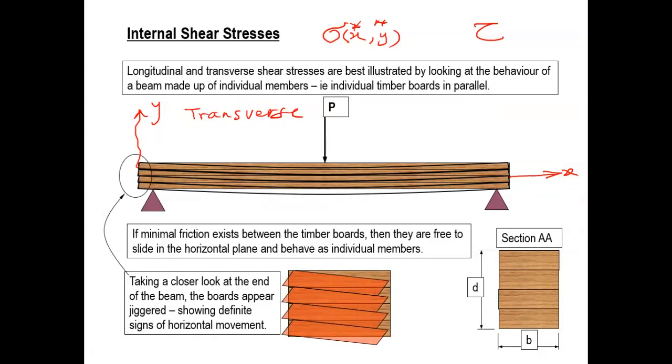X star, y star is the location at which the normal stress is maximum. Because this formula is My divided by I, it makes sense this is maximum when your bending moment is maximum. So you are searching for a position where the bending moment is maximum. That position axially is your x star.